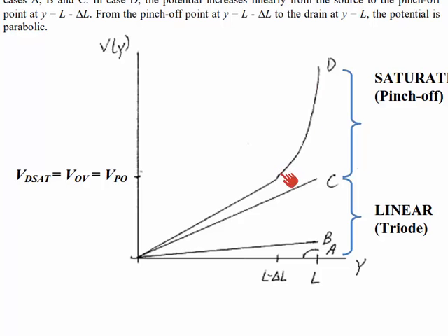And I should point out that the steep potential drop means a high electric field on the drain end of the device. And this does correspond to a place where the devices can break down. If the E-field goes too high, we can get a breakdown happening in the transistor, and deleterious factors happen there.